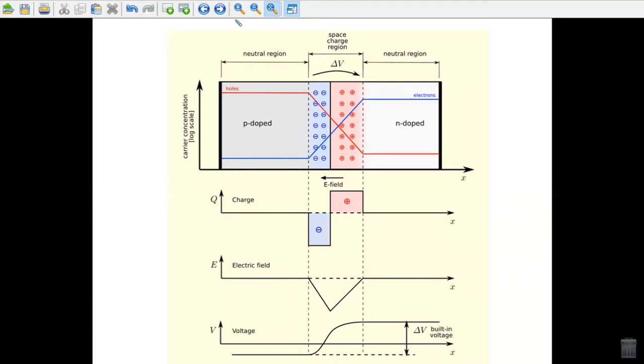Look carefully at the p-type diagram once again. Because this valence band is so close to the Fermi level, electrons tend to stay in the valence band at lower orbitals. This means that there are holes where an electron could be, which makes it a charge carrier. It's also worth noting that the diagram above isn't totally accurate, as doping normally introduces more bands instead of shifting their positions, but the concept is the same.